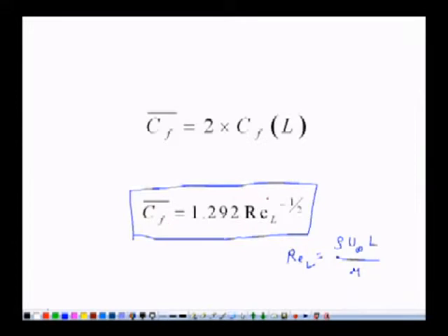Earlier, before 1904, it was not possible to calculate the drag analytically. With the help of these approaches of the boundary layer, we were able to solve the mathematical equations and give answers analytically to questions like what is the drag, what is the boundary layer thickness at different locations. Otherwise, we used to conduct experiments to answer what is the drag force on this flat plate.